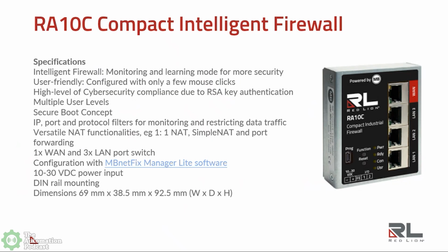So if I'm an OEM though, I can use this as a one-to-one NAT device if I don't need to use it as a firewall. That's correct. Yeah, and we do sell it that way a good bit. So any controls engineer or OEM, like you said, that is building some machine, many times it's cookie cutter. So the PLC and the IO are the same exact IP address in every one of the machines that they build. But maybe one customer buys multiple machines, and we want to pull data out of that. So when you have the same IP address or IP address duplication within your network, it's going to cause problems.